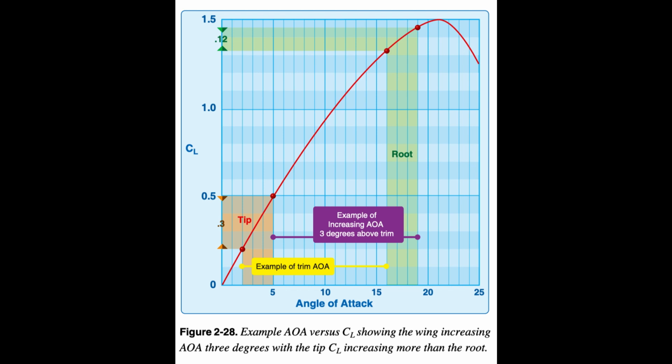In situations where the pilot is flying in severe/extreme turbulence, wind shear, or the pilot is exceeding the limitations of the aircraft, the WSC aircraft can get into a situation where the root chord is at a negative AOA and not producing lift. This could result in an emergency vertical dive situation, as discussed later in the whip stall tuck tumble section.